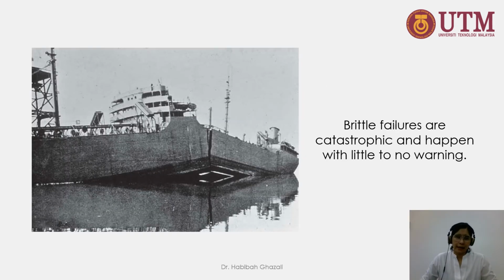A designer cares if a material is ductile or brittle because brittle failures are catastrophic and they happen with very little warning. Like the US World War II tanker here, and the Titanic also had this happen. The hull almost cracked directly in half. This was a catastrophic failure and it occurred with no warning, and it is a brittle failure because with ductile failure you can